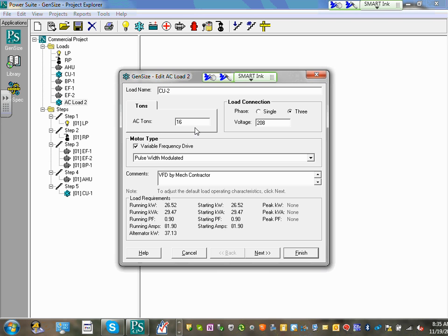That's the future one. Now, do you guys remember what the amps for that one was? The amps for the future one was 44. So let's try 9 and see if we can get 44. We're looking at 44, Adam. So let's do 8. Okay, so 9 wouldn't cut it. So 8.5, 44. Let's make it a 9 then. Now they might not make a 9. Actually, the cut sheet says 10 if you look at it. So let's put it at 10, because the cut sheet shows 10. It gives you 51.19.